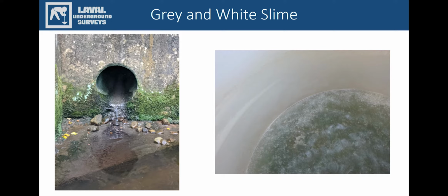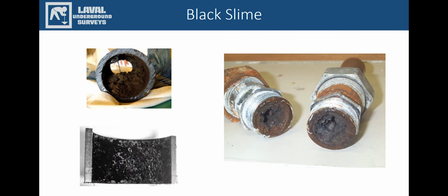These types of slime may be very rich in heterotrophic, which is organic nutrient-using bacteria, and can harbor a wide range of bacteria, including coliforms, where environmental conditions permit. Sulfur-oxidizing bacteria might also form these types of slimes, particularly in a hydrogen sulfide-producing groundwater. This black bacterial flora is dominated by SRBs.